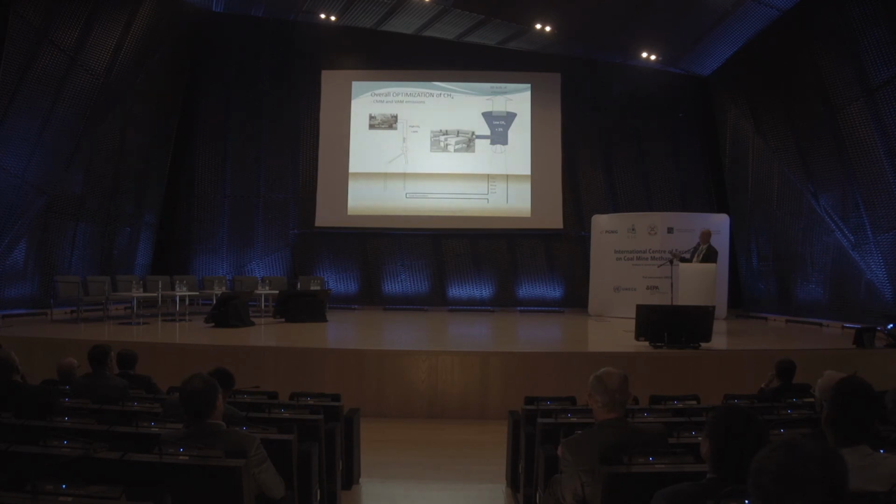So if you have a concentration which is close to 1, which is often the case in Poland, then you might look at generating electricity. And then you would be looking at taking some of the drainage gas and using that to stabilize the concentration in the VAM. And you might even look at increasing it from 0.6 to 0.8 maybe, because you will have a full impact of that increase.